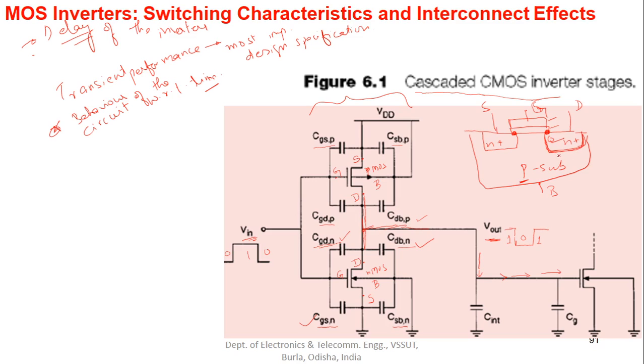We know that whether the junction is in forward bias or reverse bias, it has its own capacitance associated with it. When we operate a MOS device, we tend to keep this junction and also this junction in reverse bias, so that it does not allow any sort of leakage current. The leakage current is kept to a minimum between source and the body, and drain and the body. So there is a PN junction here, and similarly this is also a PN junction. Since these are reverse biased, the capacitances arising because of these junctions we call the junction capacitances.